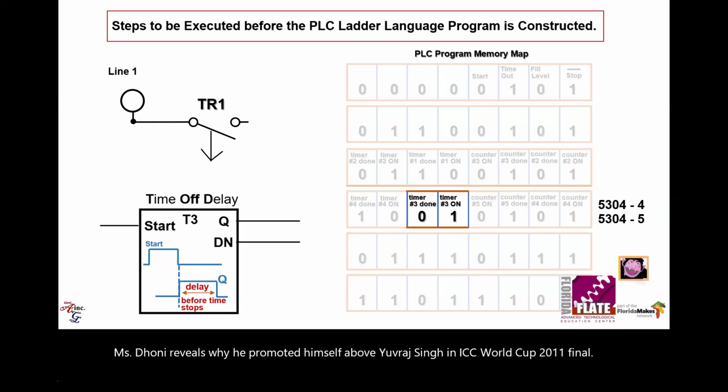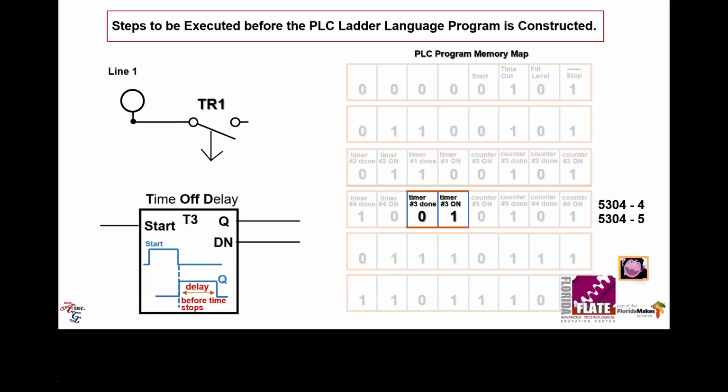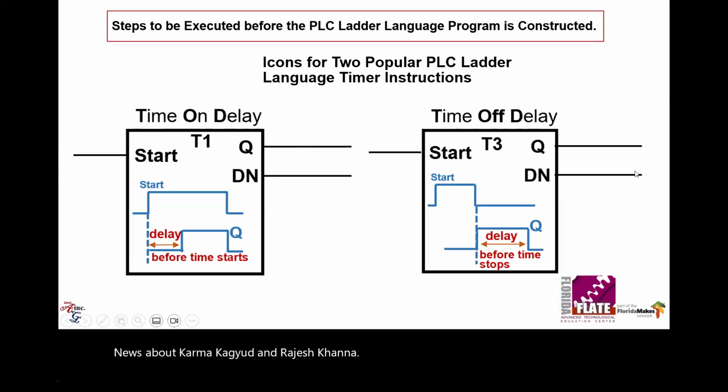So what's the problem? The problem is, a lot of times you don't think about it, but you say this is 1, 2, 3, 4, and 5. This is not bit location 5 because you're still in base 8. So this is location 0, 1, 2, 3, and 4. Don't let your students get caught in that trap and avoid it yourself. All right, there is an on-time delay, there's an off-time delay programming element.